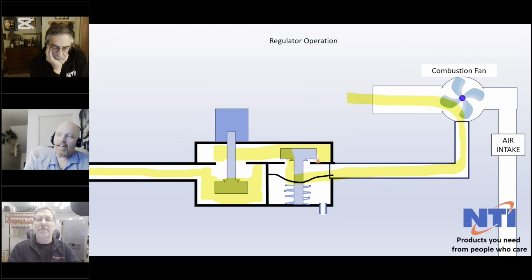And hopefully, I'm going to show you on the next slide where the gas passes through this. It's a little hard to draw because I don't have three-dimensional drawings available. But your gas enters through the vent screen here and it goes up into the top. It's prevented from entering this central chamber by a diaphragm that's controlled by the solenoid.